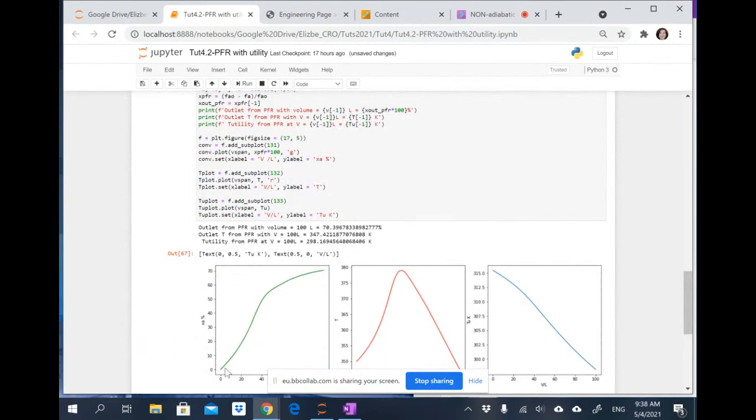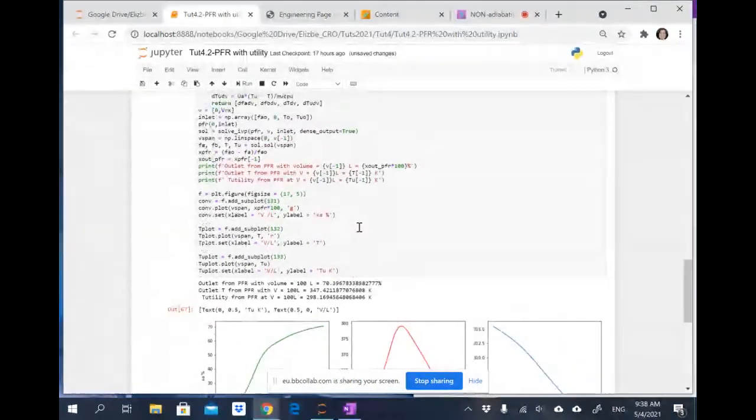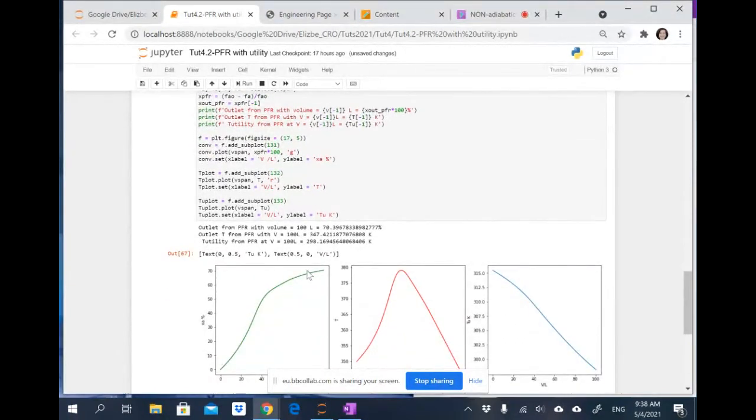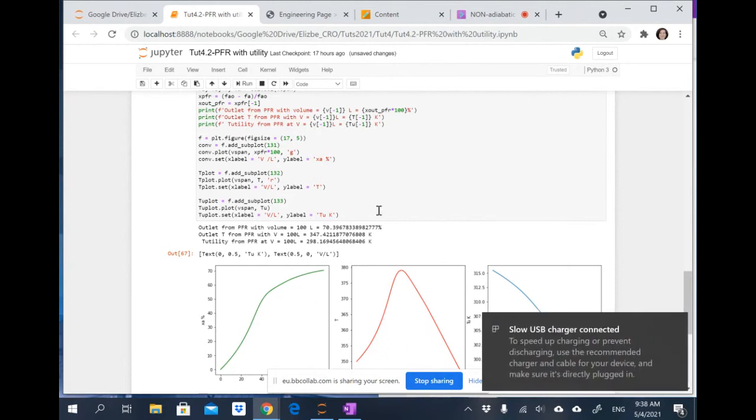So I can actually achieve a 70% conversion. It's very beneficial if I can employ this counter current. In other words, there where I want to have the highest rates, where I want to utilize the fact that I don't have much of my product available and I want to utilize the high rates that are possible, I don't want to kill that rate there by cooling at the maximum. I don't want to cool, oh my word, power failure.